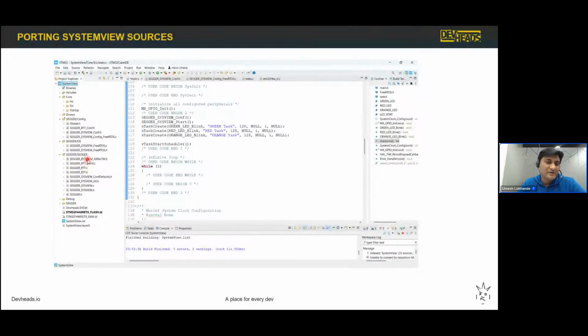And then you can see the other source files that I have added, and those are the special features that we want to add. Let's say we want to add to our project a printf style API from SEGGER. So that's why we have this RTT printf.c, and then there is the RTT API through this RTT source file, and then SystemView API access through the SystemView files. So I hope this is clear.